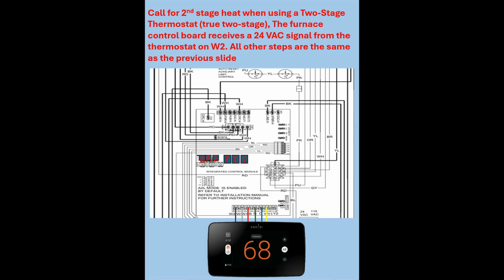I would want it to run longer on one stage. As I just told you, I'm a big proponent of letting that run 20, 30 minutes. You're running at half the BTUs, and on real cold days, it's already caught up. So it's not going to freeze you out. And if it does, we'll just go to second stage.